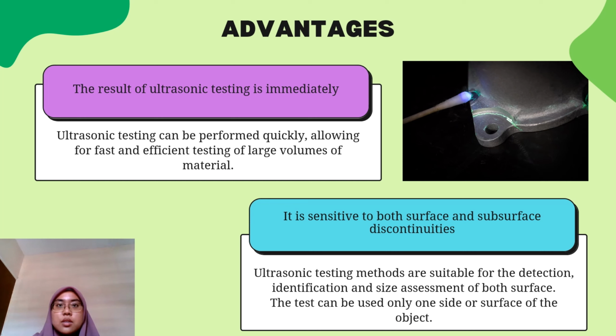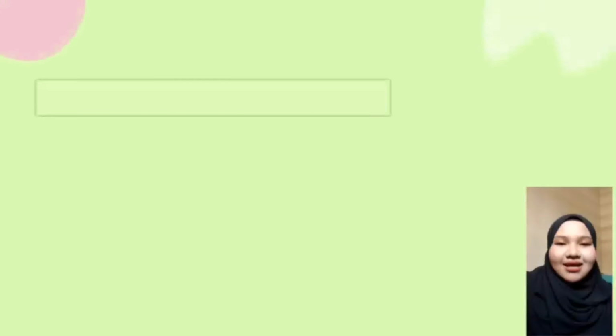The last one, ultrasonic testing is sensitive to both surface and subsurface discontinuities. Ultrasonic testing methods are suitable for detection, identification, and size assessment for both surface and subsurface discontinuities. The test can be used on only one side or surface of the object.